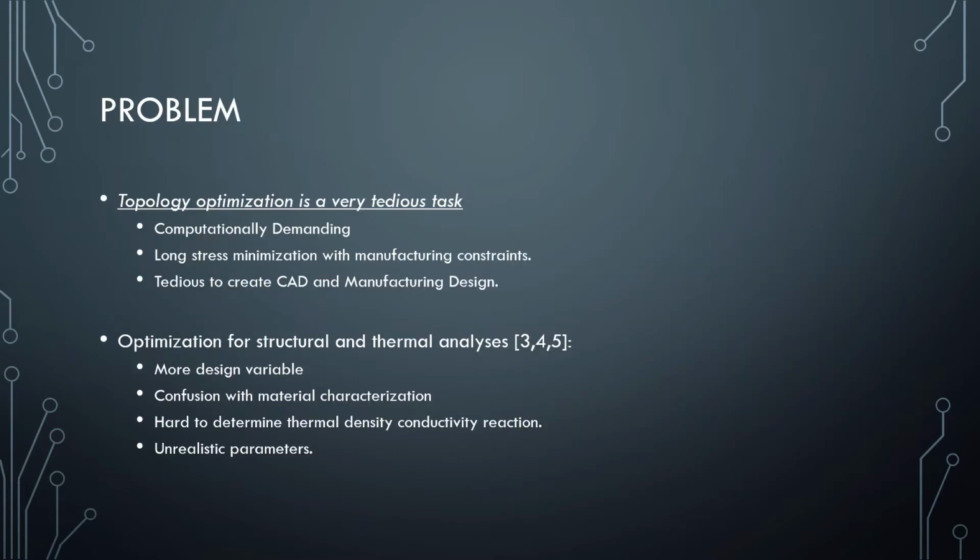In short, designing using topology optimization is a very tedious task. Computing the optimization is computationally demanding and can take several to many hours to complete a simple compliance minimization problem. On the other hand, stress minimization and the imposition of manufacturing constraints can take several days to complete.